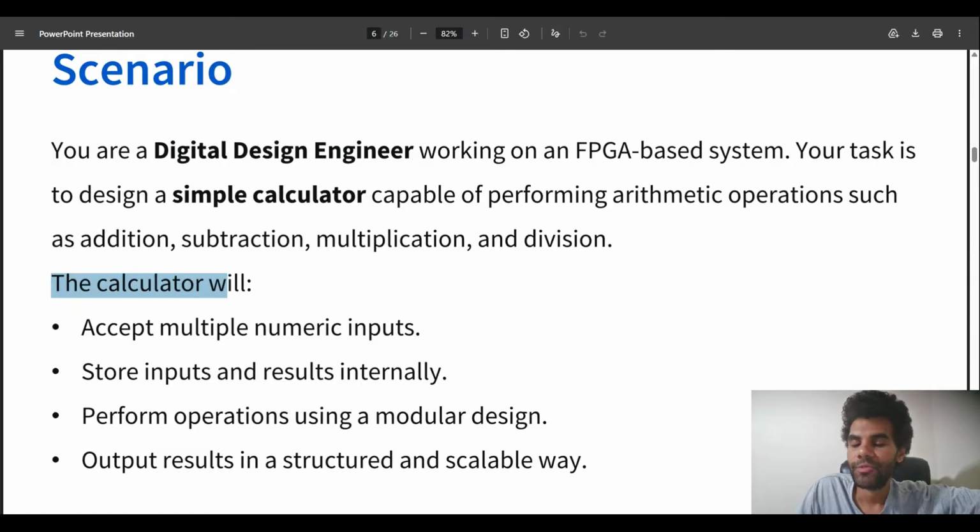And of course it has to be saved in a kind of FIFO, for example, to take the number one and then seven and then three and then two, and you write it down in the FIFO. Then while performing the calculation you want to read it out. So this is something to be taken into consideration. We need to store the inputs, so we want to use a FIFO, and then perform an operation, which is the ALU.